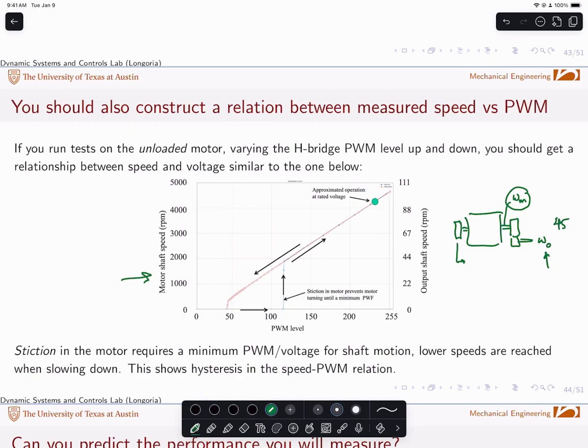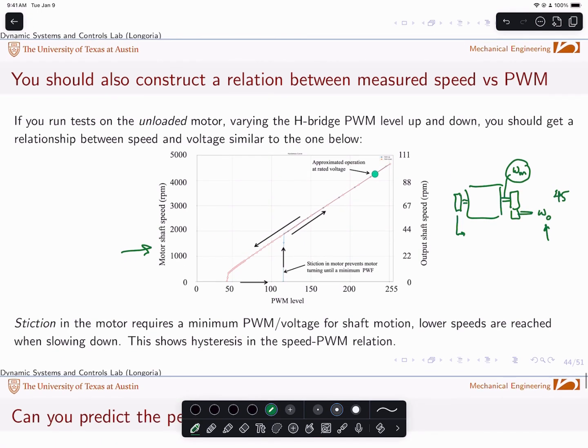So when you're comparing to the spec that the manufacturer gives, the 9 RPM, or what is it, 90 RPM, that's what you should be thinking about. So check here, in this particular data, it took a value of 50, not 0, to get that motor going. So note, the motor does not start rotating. See here, it hasn't moved until it gets here. That shows that there's some stiction in there. It takes a little bit of oomph to get that thing going.